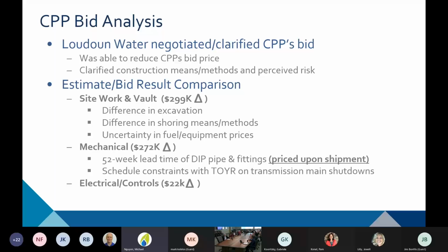And I think the heart of your question as well, Mr. Koblis, is, I believe, and I'll let others correct me if I'm wrong, the engineer felt pretty confident that shoring would not be required, as this is not an extremely deep excavation. There was some known geotech work done, albeit I believe just one boring at the vault location.